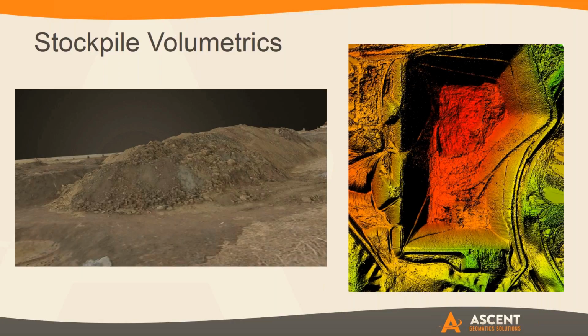Yeah, absolutely. With anything in life, there are relative and absolute accuracies. With LiDAR, we can develop true absolute accuracies down to pure survey grade, call it 0.05 of a foot or less, depending on how tight the control survey is. Whether you're flying photogrammetry or LiDAR, your control is what guides the entire project. So no matter what, we're still surveyors on the ground really defining that, because that creates your good quality. So LiDAR is incredibly accurate. You can get an absolute accuracy.